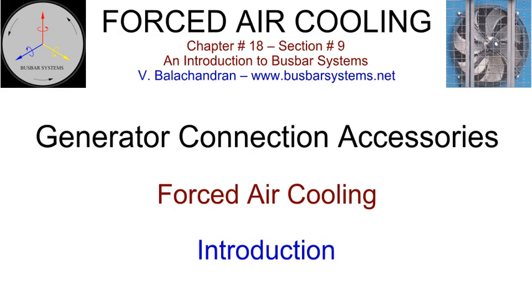Isolated phase bus with rated current above 25 kA tends to be forced air cooled to reduce the overall size of the bus enclosure and conductor. This requirement is necessitated to meet constraints of space near the generator and indoor area of the station, ease of manufacturing, transport, and installation, and to reduce the initial cost of the installed equipment.